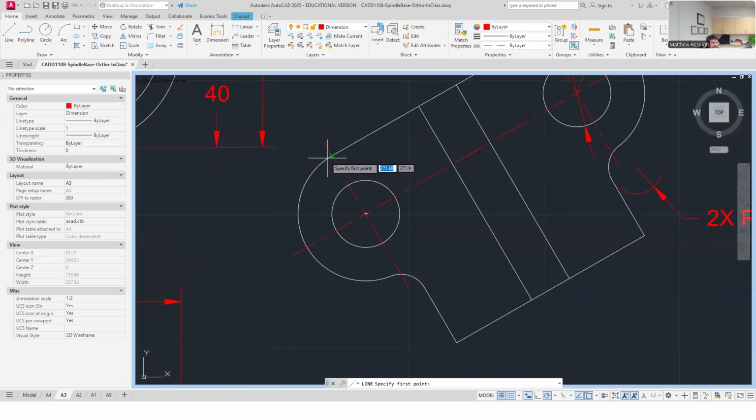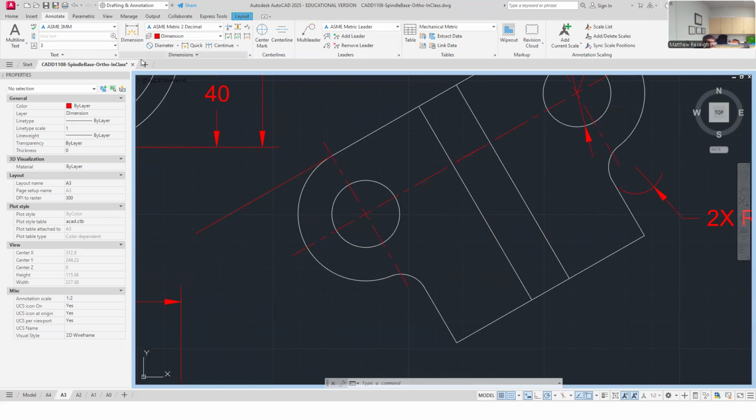And I'll just come in here and draw my own little extension line that's orthographically aligned with my view, whatever degree that is. I happen to have a snap because I think we're on a 30 degree, a nice orthographic projection plane actually. And so I can use my snap here, because you'll notice when you're doing aligned dimensions on something that's not in an X and Y orientation, it's harder to snap that and move that dimension around. So I just do this as a cheater.